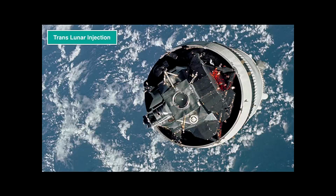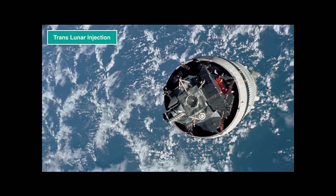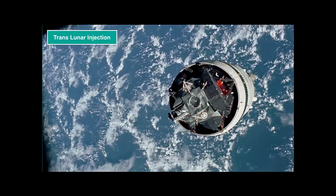Now that we know how to orient ourselves and how to control the spaceship, it's time we fly to the moon. Usually, the translunar injection happened in the middle of the second orbit around the Earth, so around 2 hours, 45 minutes into the flight. This is still performed by the 3rd stage of the Saturn V, so the Apollo guidance computer once again should only have a passive role here by monitoring the translunar injection with a dedicated program P15. After separation from the S4B, we are on our way.